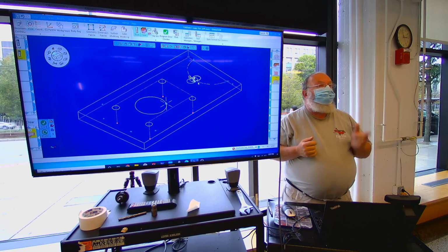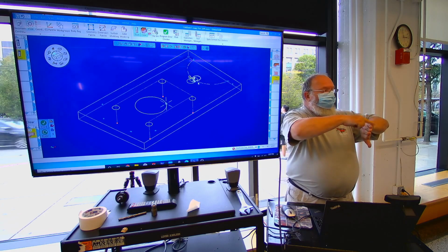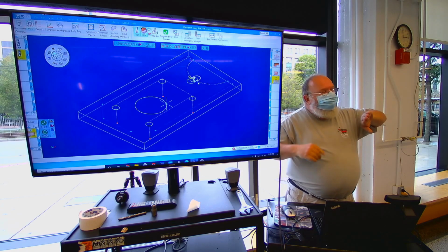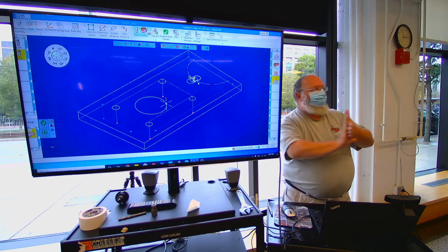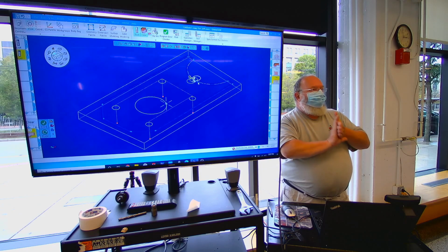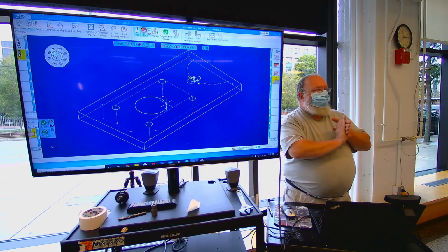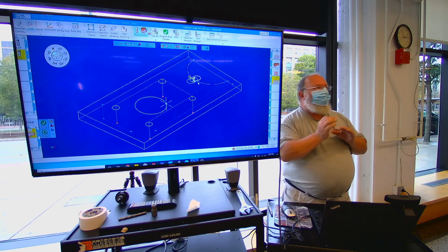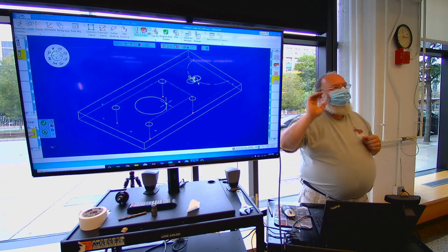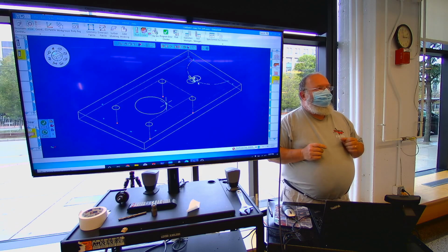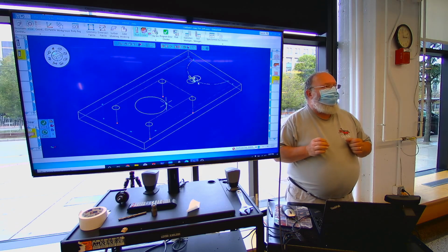Well, that breaks tools in a manual machine. So what we do is we change the feed direction to conventional so the forces are constant on the screw and there's no play. Now you can take climb milling chips in those manual machines, but they're very small, okay? Now, how did they eliminate backlash in these? It's a rather ingenious invention called the ball screw.